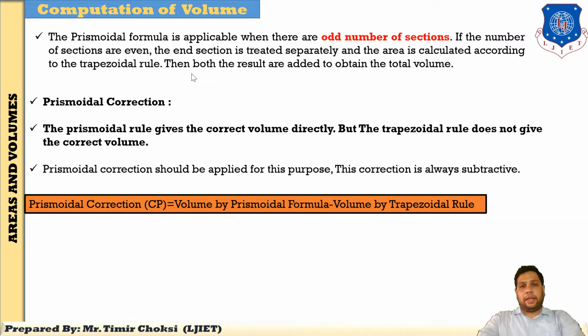So when in an example 10 ordinates are given, meaning 10 heights, an even number, for instance 6, 10, 4, 12, then with 10 cross-sections, the volume for sections 1 to 9 you find from the prismoidal rule, but for the last sections 9 and 10 you find the volume using the trapezoidal rule.